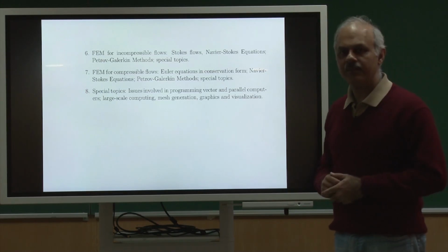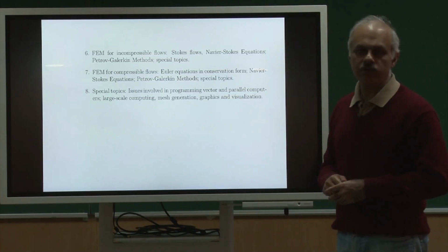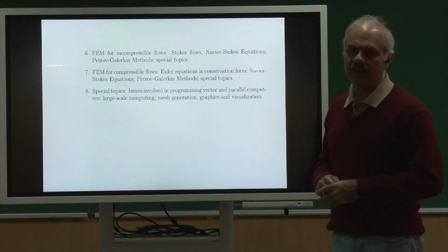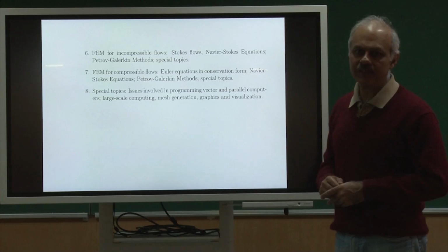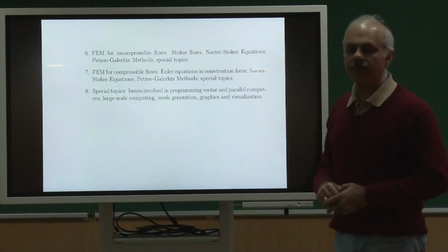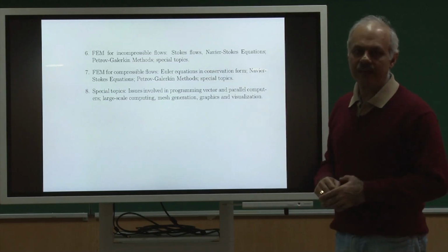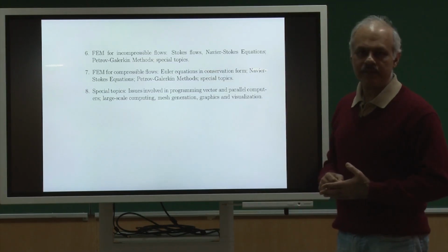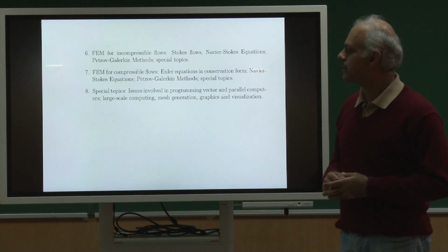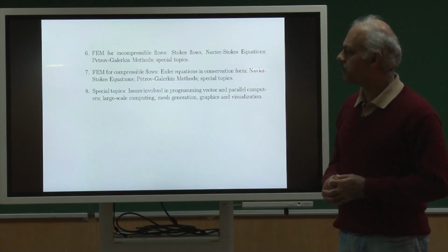You are already familiar with a method like Newton-Raphson, maybe the secants method. So we will briefly go through those and look at what are the limitations of those methods, when do they work, when do they not work, and then we will be ready to go to incompressible flows. Now these are extremely complex problems. If I compare a flow problem, let us say with incompressible equations, to a heat conduction problem, then the challenges are quite complex. As you are aware, the continuity equation makes a big challenge.